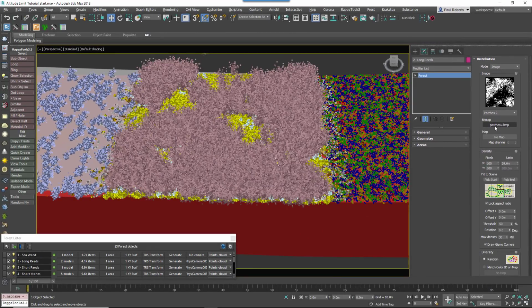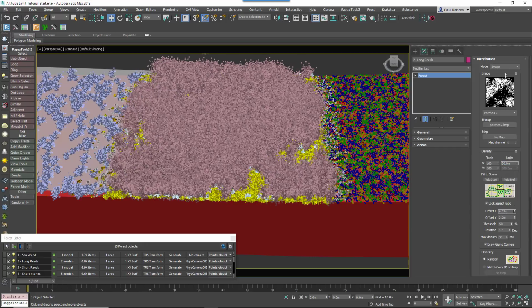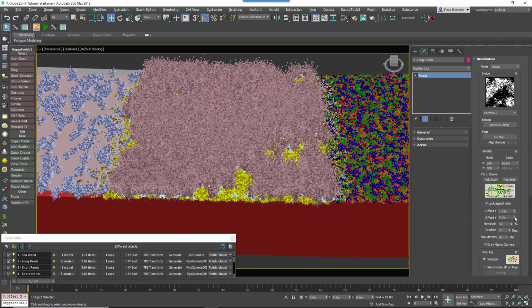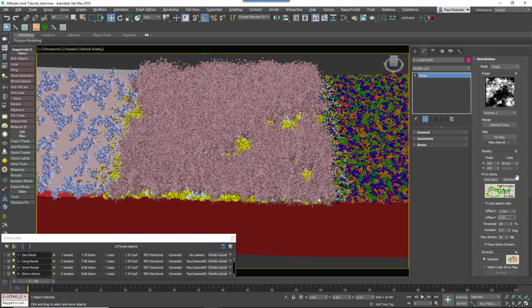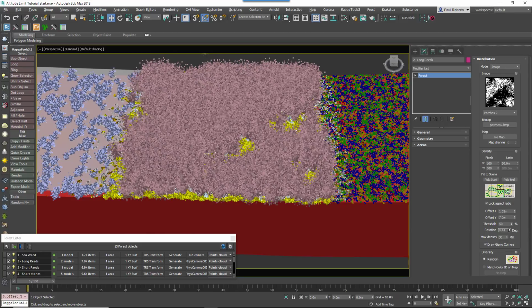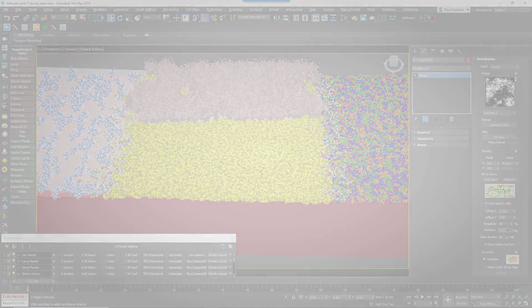Now that we have a pattern that works, it might be necessary to adjust the density as well. In this example, I've reduced the value to 15 meters to add additional reeds. You can also move the distribution map around the scene using the Offset X and Offset Y properties. This is particularly useful if you want to layer two or more forest objects that use the same distribution map and similar densities. You can also rotate the map too for even more variety.